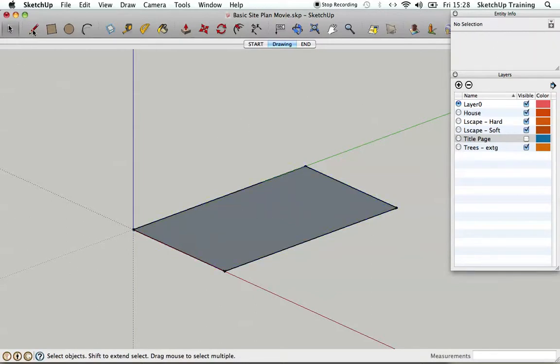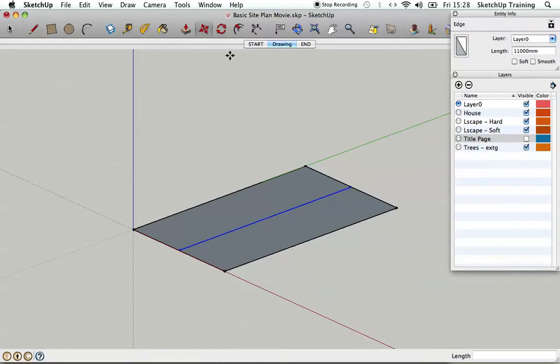So now if I draw a line, you'll see that this line, when it's moved, if I've done it correctly, shouldn't actually affect the rectangle below. So I've drawn my line again, I've selected it, I've hit the move command. Now this time when I lift it, bingo, there you go, I can move the line independently of the group. So I don't need that line anymore. We've shown how groups can be used, at least in principle.